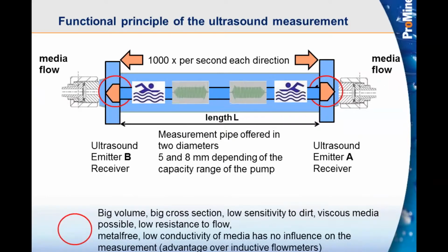So from that and from the volume, the cross section, it knows the volume. It can calculate our flow rate through that device. So now we know our instantaneous flow rate. From the instantaneous flow rate, it can display that instantaneous as well as start totalizing how much flow has gone through.